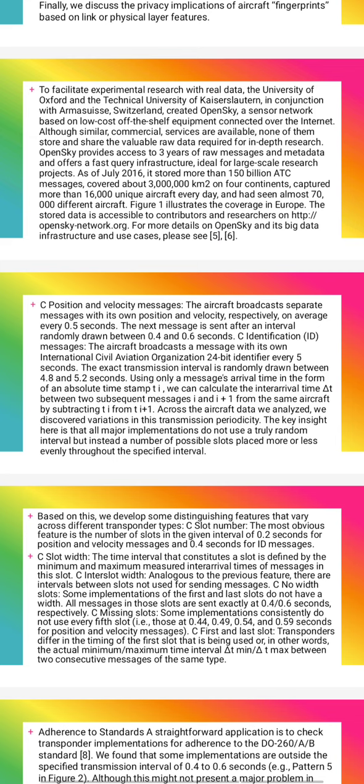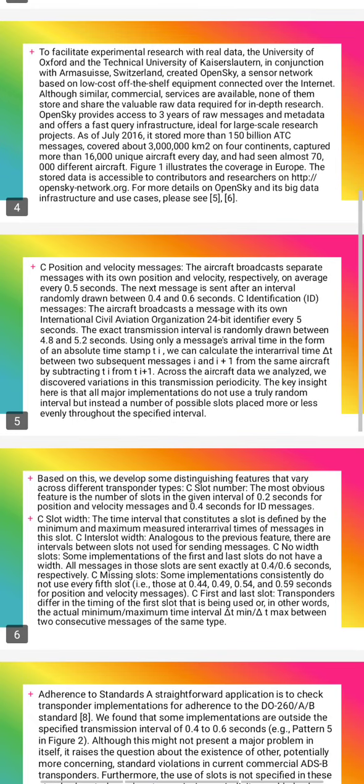Identification (ID) messages. The aircraft broadcasts a message with its own International Civil Aviation Organization 24-bit identifier every 5 seconds. The exact transmission interval is randomly drawn between 4.8 and 5.2 seconds. Using only the message arrival time in the form of an absolute time stamp,